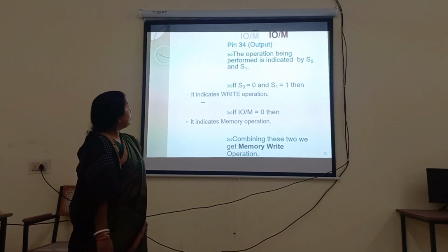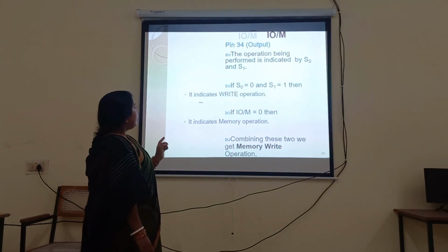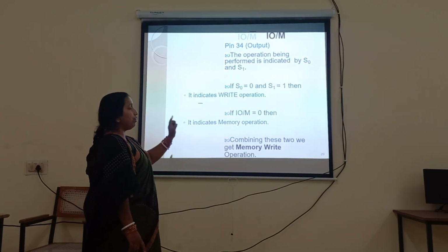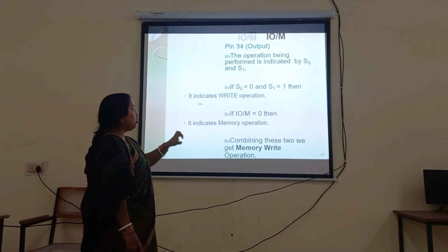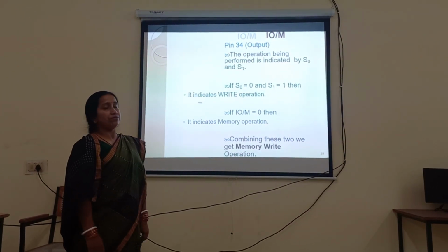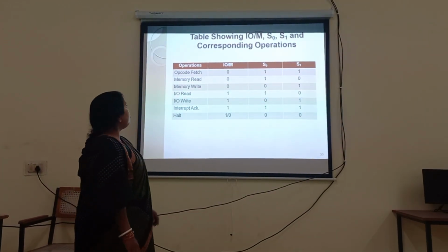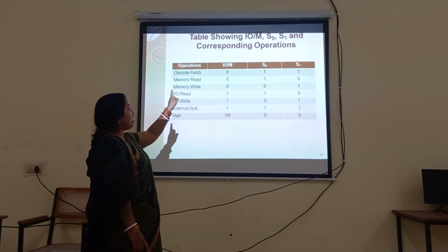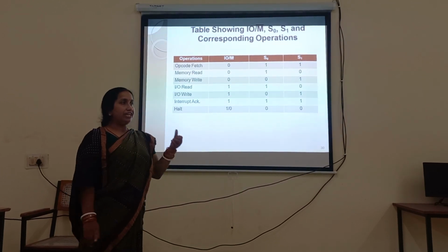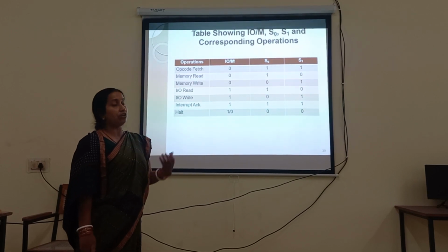Then next, on pin number 34, the operation being performed is indicated by S0 and S1. Here, S0, S1 and IO/M bar together are needed to explain the execution of the program. So we need to know the IO/M bar status, S0 and S1 status, so we can study the read, write, halt kind of operations done with the I/O or memory.